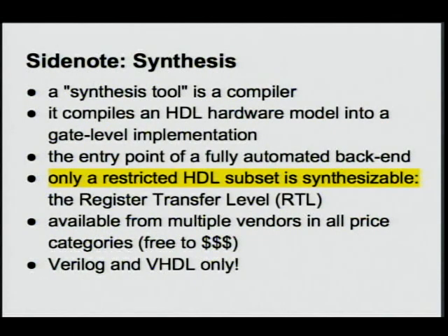Now I have to make a small side note and tell you about synthesis. Because in hardware design, we don't have just one compiler, we have two compilers. We have one that we use to compile to a simulation database so that we can simulate and verify the design. And then we have another very important compiler, which is called a synthesis tool. A synthesis tool is a compiler that compiles an HDL design into a gate implementation.